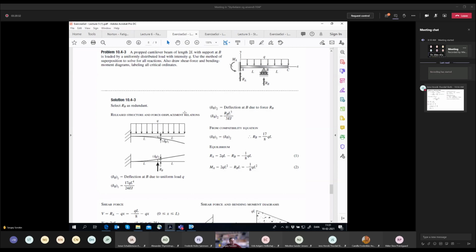Yes. So now we take a look at this picture, and we see that we have here L in the table, but in our case the length of the beam is twice L. You see, you have L and L, right? So the total length of the beam is 2L. So now it means that you have to use this formula for v with a small modification.